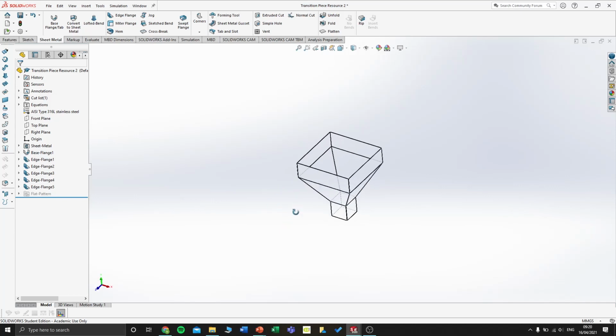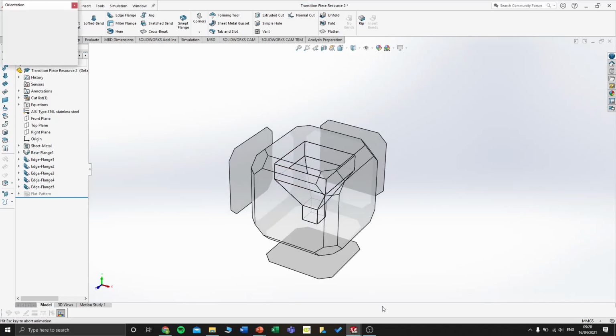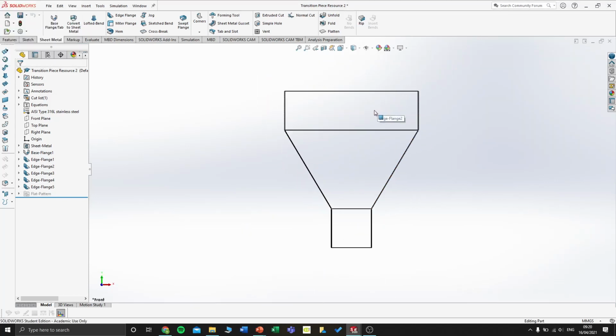Now, I can still see the outline of the shape, but what I'm trying to demonstrate is the true lengths, because the main problem that we're having in classes is understanding what true lengths are and visualizing them. If I want to see if this line is true length, I want to look at this perpendicular. I'm imagining this is my elevation. This line will be parallel to the XY line, so that means the line is a true length in elevation.